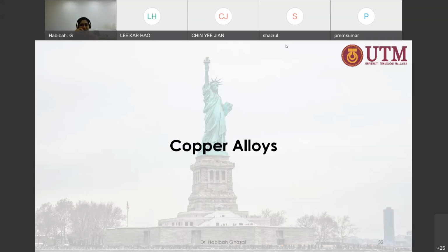But since you asked, when I discuss that homework, once I finish marking all of them, I will explain to you how it happened. Okay? Okay, thank you, Doctor. All right, no problem. So that's the difference. When we introduce copper into aluminum, it actually induces stress corrosion cracking. But when we introduce aluminum into copper, as you said, it actually improves the copper